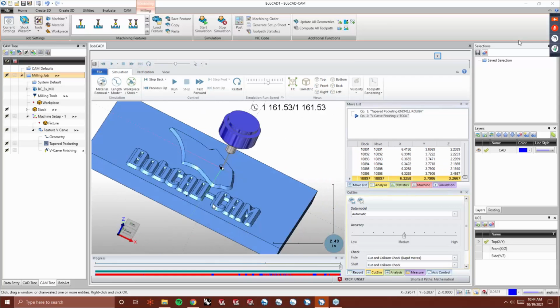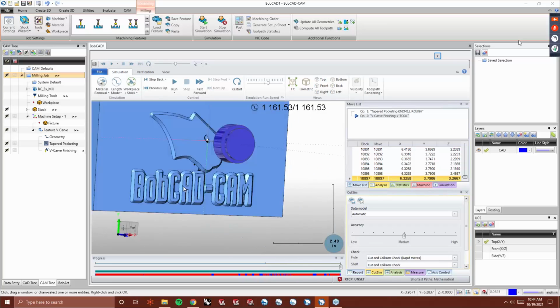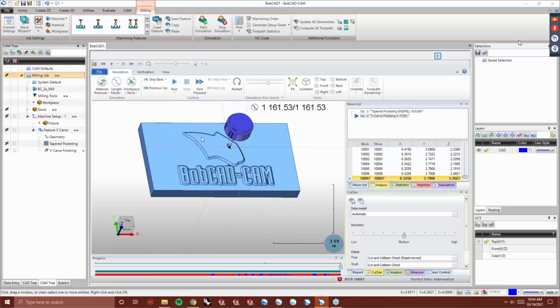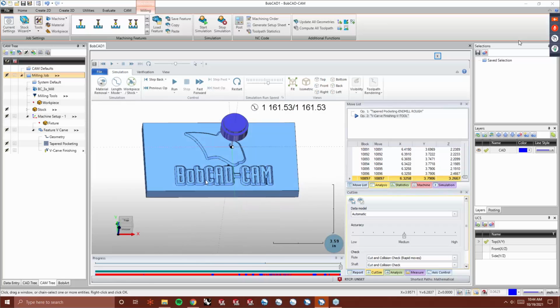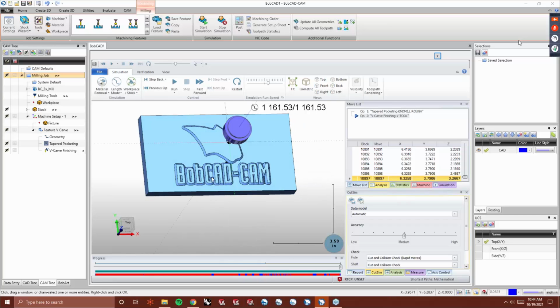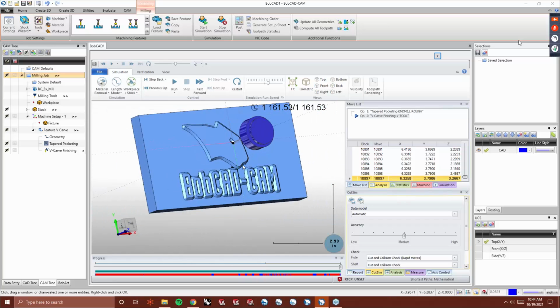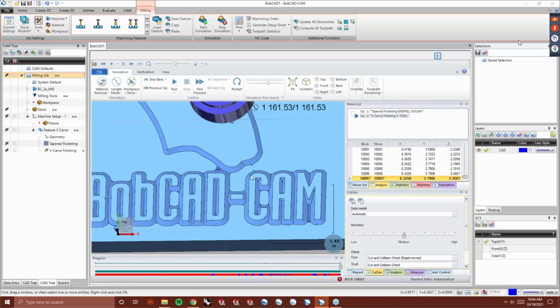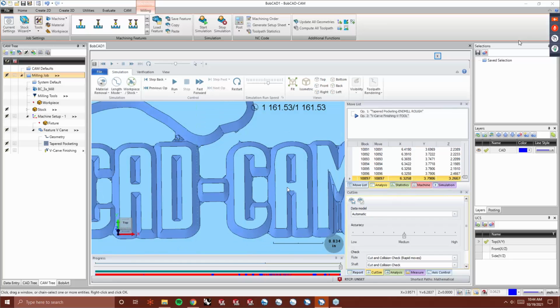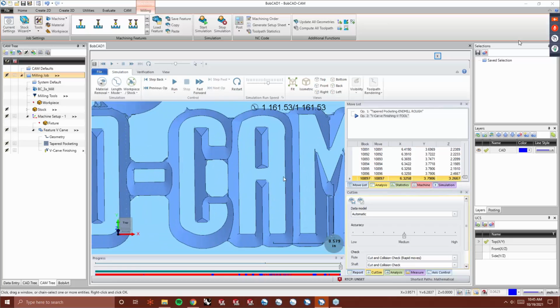Now it's going to still run the toolpath on the outside, but at least now I have a flat wall or a flat floor all the way across. So there is no open pocketing. You can't do the dashed lines, but you can still offset and create an open pocket. VCarve can be a lot of fun. There's a lot of cool things that I've seen people do with it. But again, you are going to see more detail of geometry. It's going to be different detail, but you are going to see more detail out of the geometry.